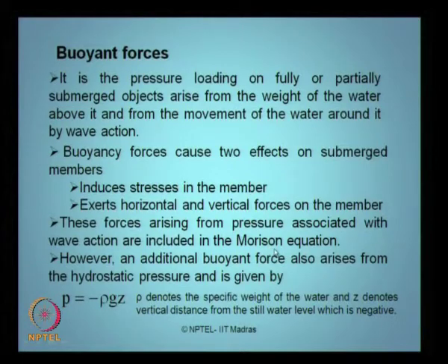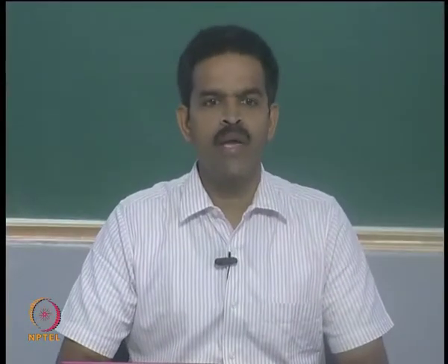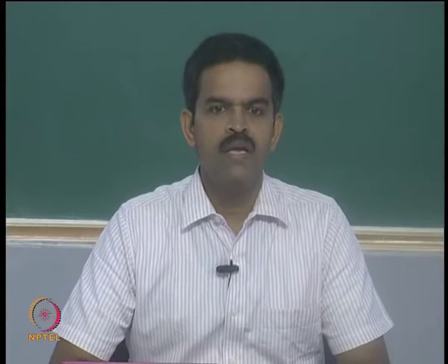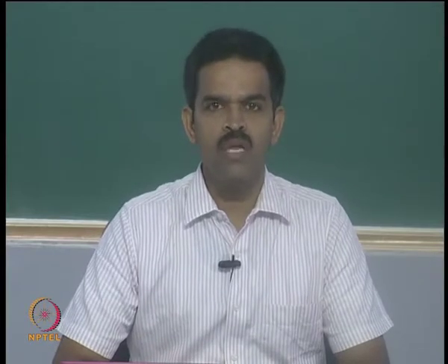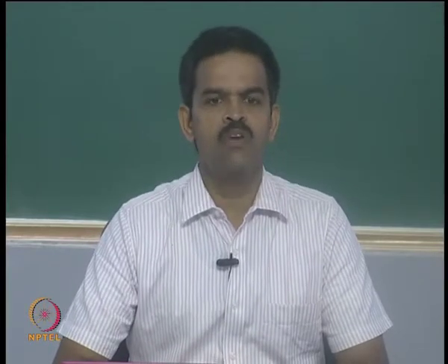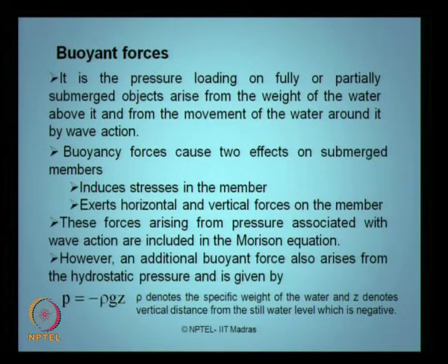Let us look into the other type of force, what we call buoyant forces. It is a pressure loading on fully or partially submerged objects arising from the weight of water above it and from the movement of water around it by wave action. Buoyancy forces cause two effects on submerged members. One, it induces stresses in the member. Two, it exerts horizontal and vertical forces on the member.